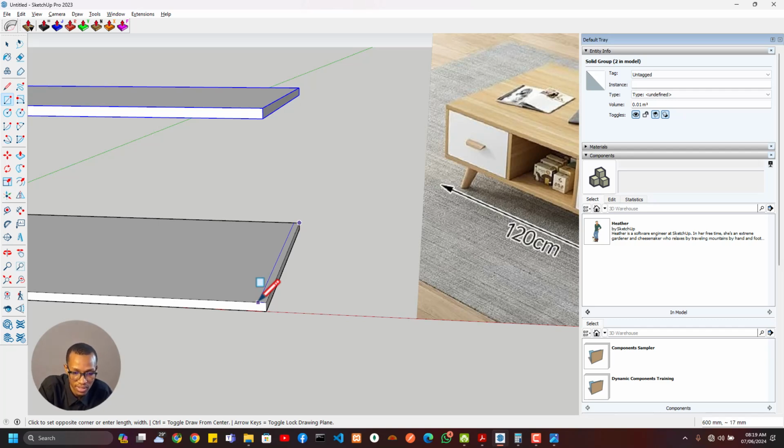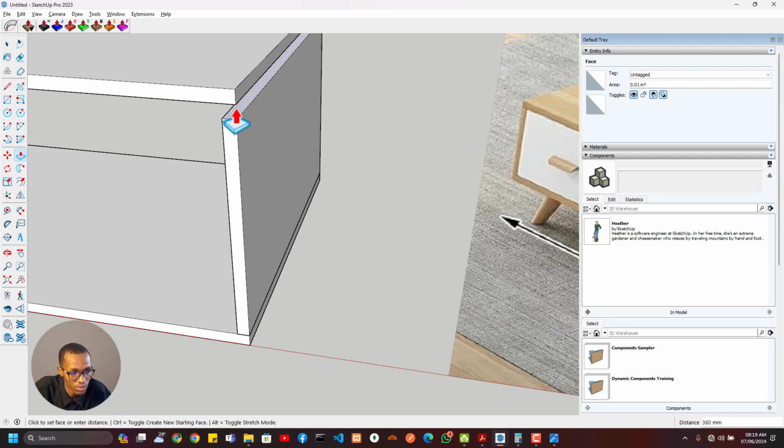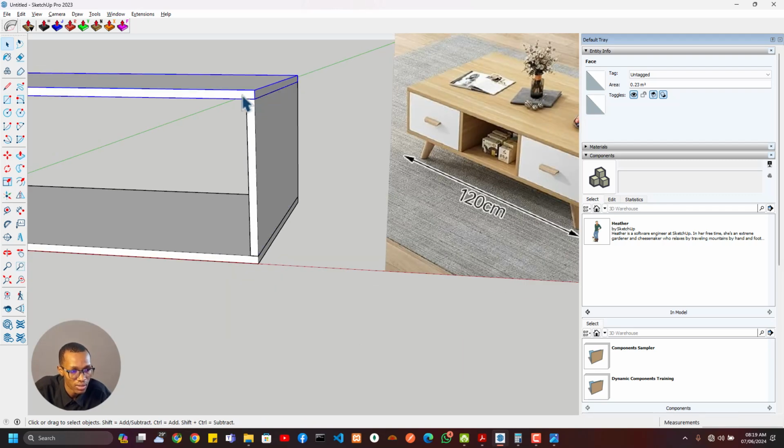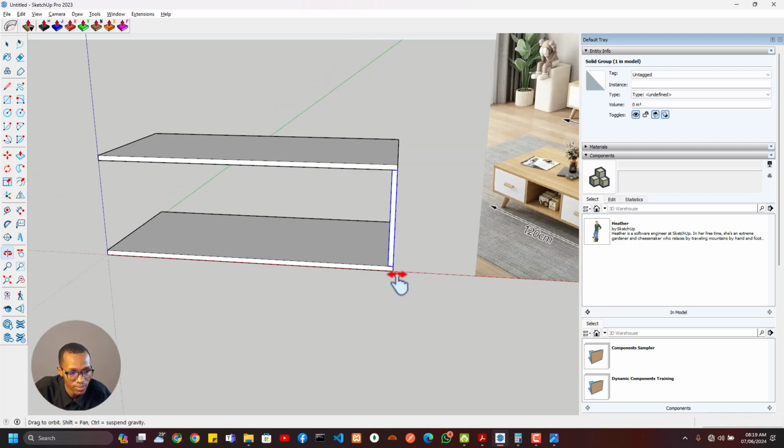I won't type anything, then I'll press comma to leave the 600 there. Then I'll now type in 20. Then you see, I get that shape going on there, and I'll push pull that up all the way till it clips. Then I'll group that as well. Make that a group. Then I'll just duplicate that to the other side.